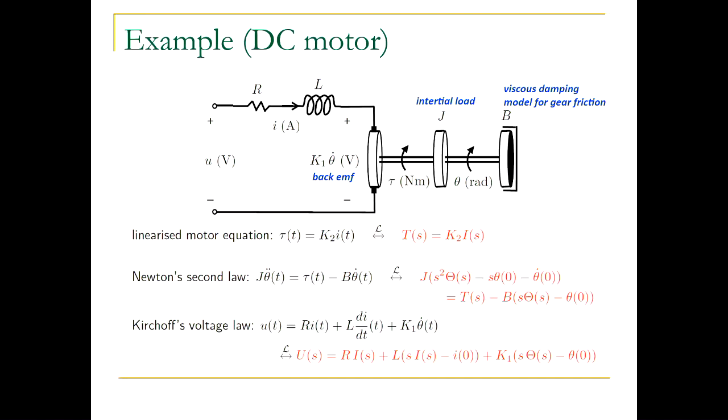How does it start moving? Well, it will depend on these differential equations. It will depend on the motor, and the motor will basically determine what R, L, and this K1 you use, because these things depend on your motor, right? So these equations depend on a particular motor. A larger motor would have different constants from a smaller motor. The differential equations will be different.